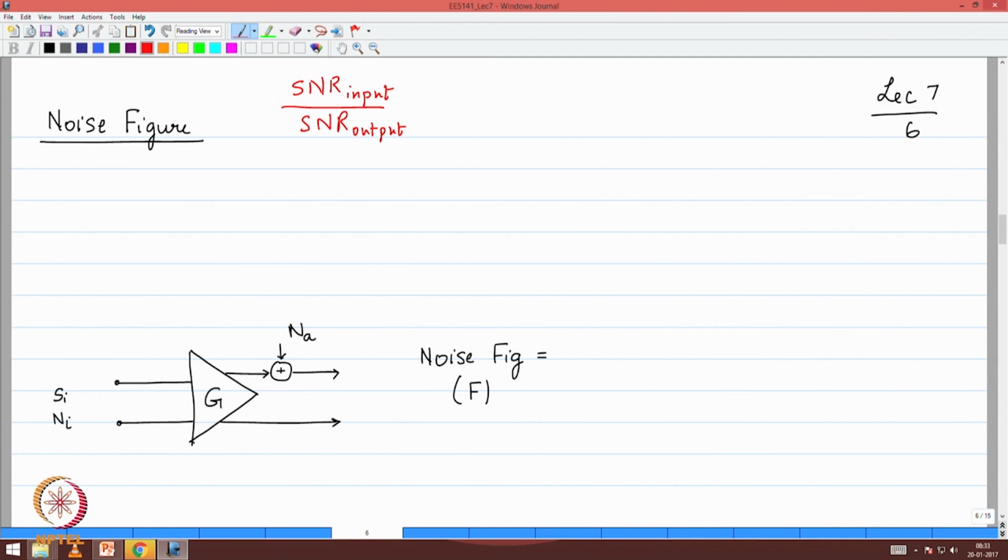Okay, so the total noise at a receiver, which I have understood it to be kTBF. K is the Boltzmann's constant, T is the ambient temperature, B is the bandwidth, and F is the noise figure. That's how you have calculated, and that's how we have done it. Now I want you to visualize this in a very interesting and novel manner. To split this as kTB, that is ambient noise, ambient noise without the receiver.